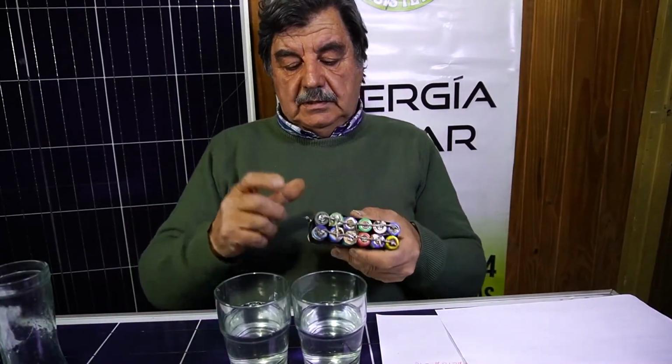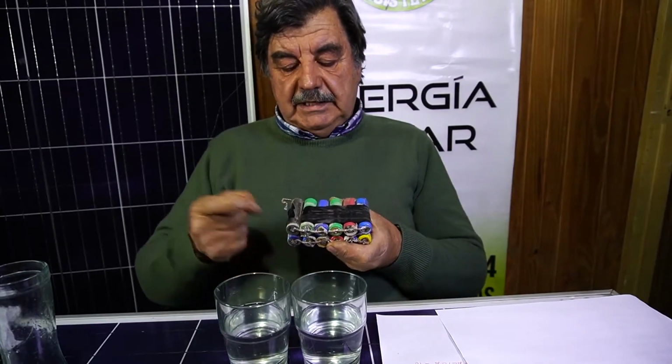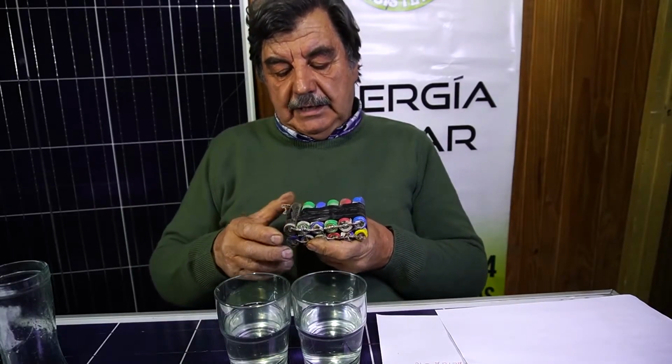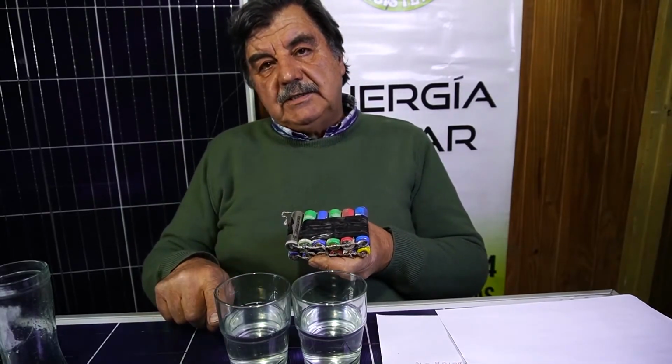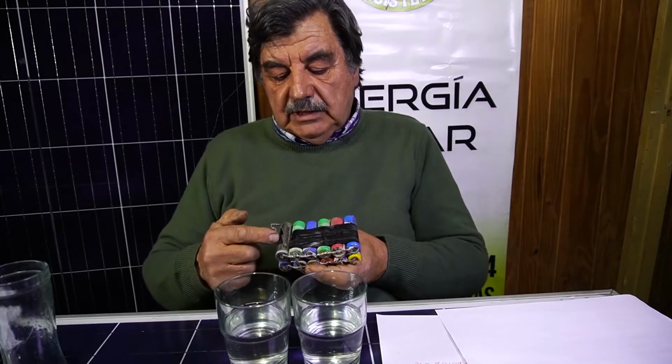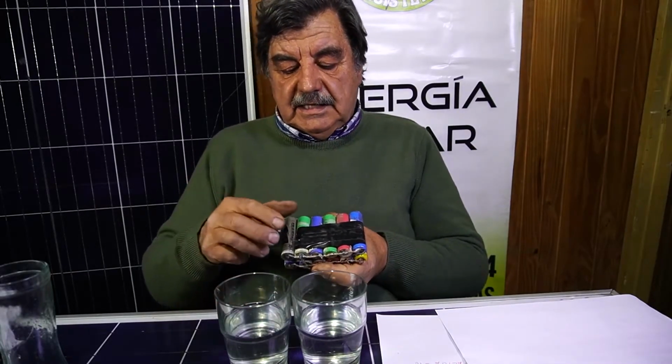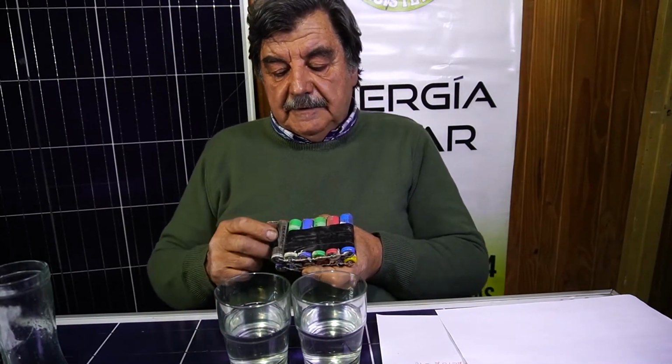That is why, when building these packs, one tests how many milliamps this battery gives, how much this one gives, and we add the same number of milliamps so that they all reach their maximum level at the same time. This function is done by the BMS, which is a simple charge controller. It has a lot of cables, a cable for each of the cells to read. If a cell has more, it stops injecting; if it has less, it injects more, and in turn